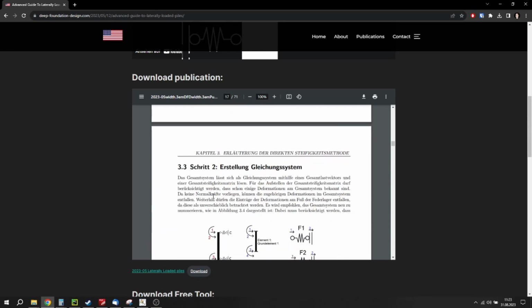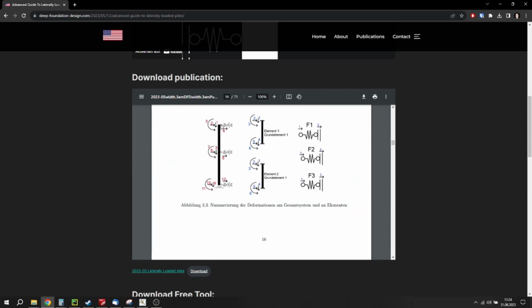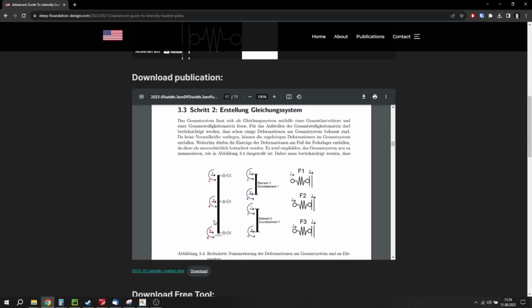Obviously, we can reduce the complexity of the system, because we are not really concerned about the vertical forces in this place, because the vertical deformations are going to be very small. And when we talk, for example, about vertical loading and eccentricity, we can describe the eccentricity at the top as an additional moment. So we can always catch eccentricity at the top with the leverage of the eccentricity times the normal force that is loading the system vertically, describe this as an additional moment, and then we just add this at the top node, so to speak. And so vertical is not really a point of concern here.